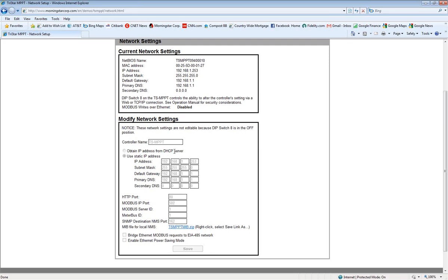One question that came up in the last presentation is, what about security? We don't have password protection. This isn't a server. It's difficult to put all this stuff in a chip, and it's also hard to keep up with the changing environment on the internet because it's changing so fast. So what we did was you can disable the ability to write data over Ethernet. If you physically flip the dip switch inside the TriStar, that's the only way you can enable remote modification. It ships in the default disabled mode, okay? And that's very important because this way everybody can look, but they can't screw it up.